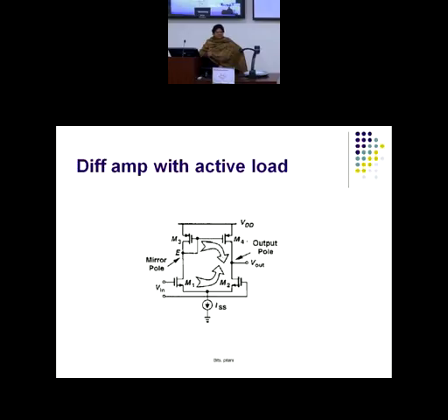Got it? I am not saying that zeros are positive or negative, nothing. The moment I have more number of zeros and poles, I have a feeling that frequency response will be degraded. So now you try to estimate the poles and zeros. Because normally in any op-amp, the differential pair is the first stage. So it does not have any stage previous to it. That means our input is fed directly to it.